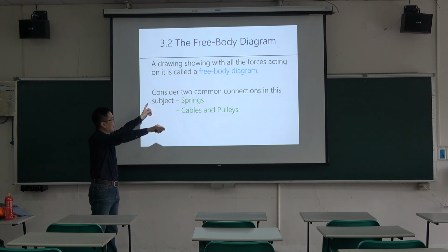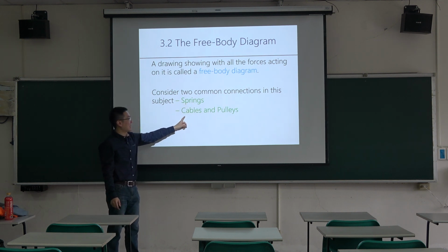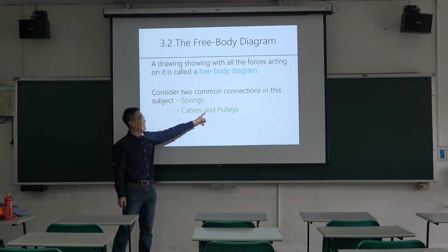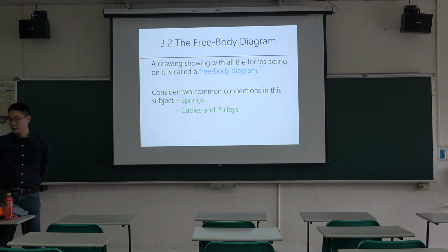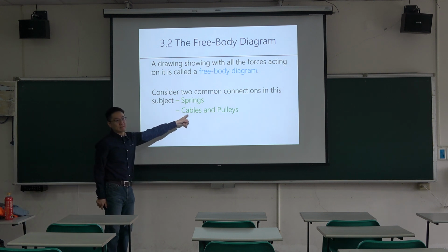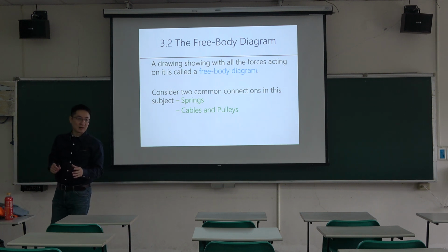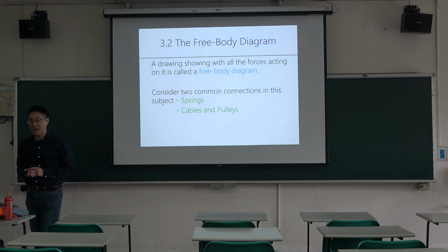Here we have to mention two common connections in this subject. One is springs, the other is cable and pulley. For springs, we will use Hooke's law to analyze the effect. A cable is flexible, so generally when force is applied to a cable, there must be tensile force, because it cannot provide compression. So the cable's effect is tensile.